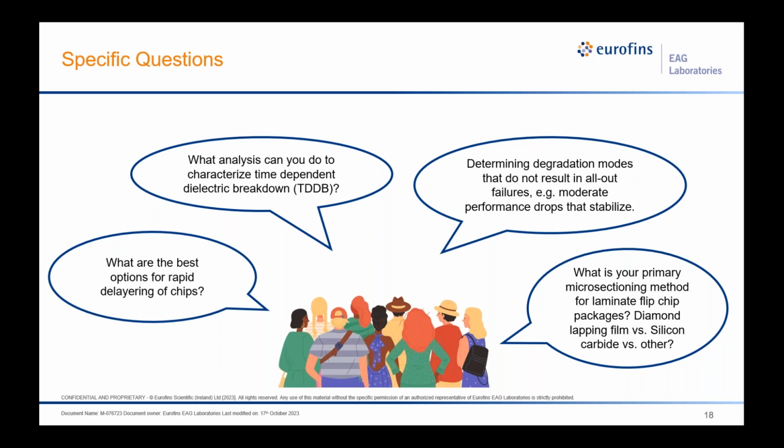And so we have to understand what the history is. That's why we ask a lot of those questions at the very beginning, because it gives us some insight about the potential things that could have gone wrong. Could it be a fab process defect, something in the application, process variation, part-to-part variation? Ideally, we want to first identify the best way to replicate the failure so that we have something to chase. That replication might not be very consistent, and it might not last very long. But if we can replicate it first, then we start understanding whether there are other environmental variables involved. Did it need temperature, humidity, vibration, radiation, mechanical stress, whatever the environmental variable? Did it need another variable to actually go into that failure mode?